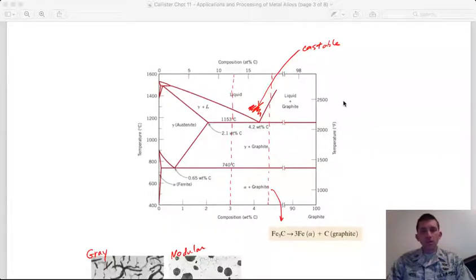you have a lowering of the melting point. And so here, typical steels would melt in the region of, say, 1600 C. For these cast irons, at say 2.5 to 4 or so weight percent, you have this significant decrease in the melting temperature, and so now you're getting melting at 1150 C, and so you start to see cast irons being cast, having the molten material poured into a mold, and we'll talk about some of those various ways of doing that later in these notes.